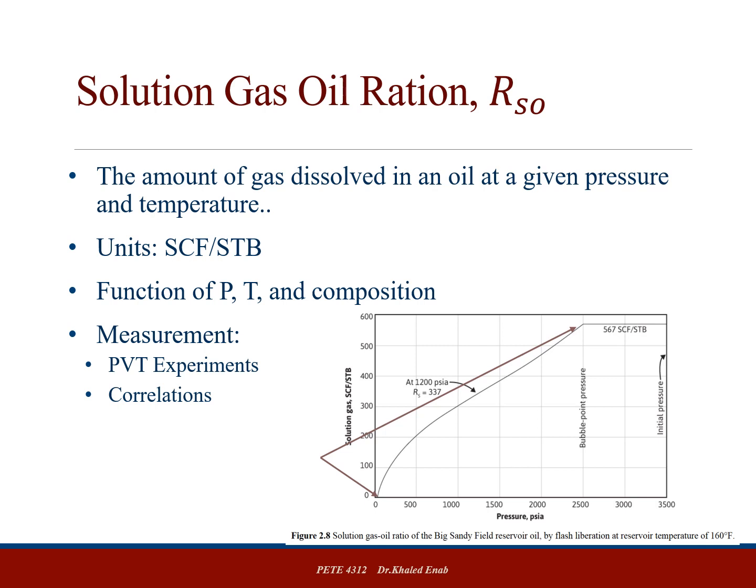So you notice that in the first part right here, from initial pressure all the way to the bubble point, the Rso, or the solution gas oil ratio, does not change because there is no more gas added, right? We reach the level where the gas is not added.